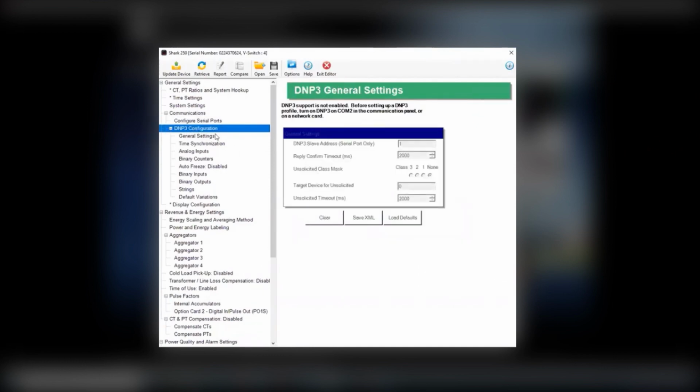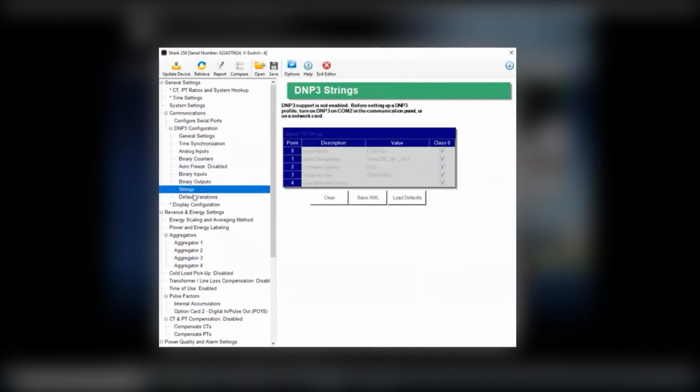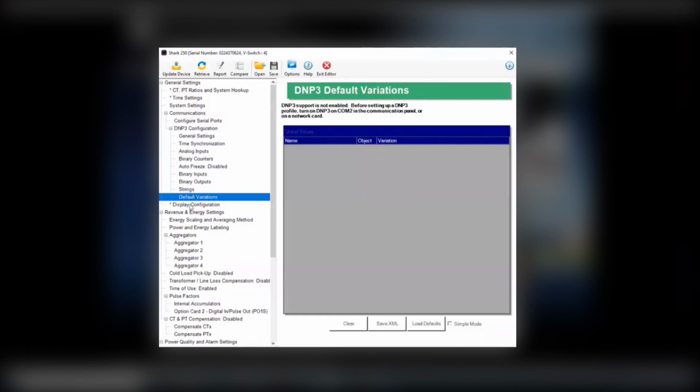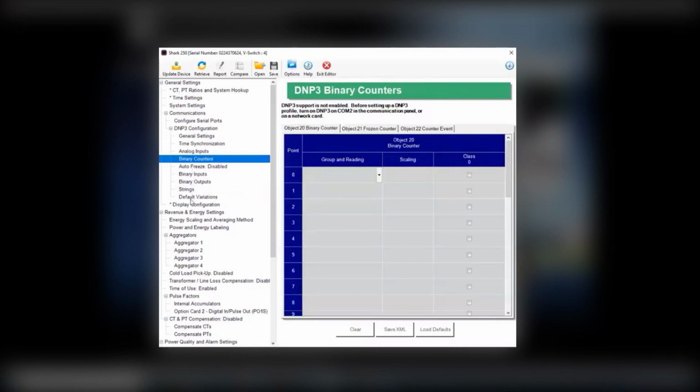We talked a little bit briefly about DNP3. You have to enable DNP. This is an area where you would go in and retrieve your SCADA information. Typically, if it's something that you would be turning on, it is driven by your SCADA or RTU folks, who would tell you that you need to have this enabled so they could pull DNP from an RTU. So this is the area where you would go in and turn that on. All of these are parameters associated with DNP setup. This in itself is a lengthy presentation, so it could be reserved for another time with a totally different discussion.